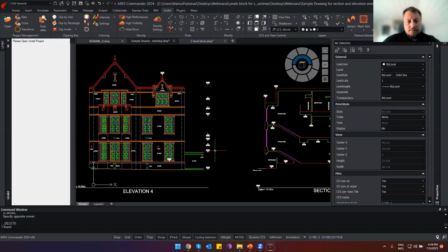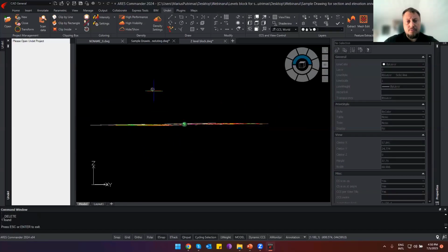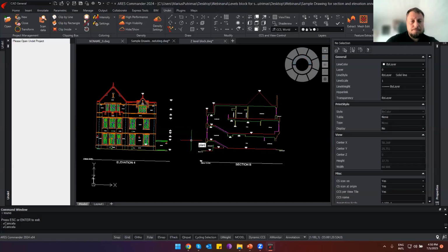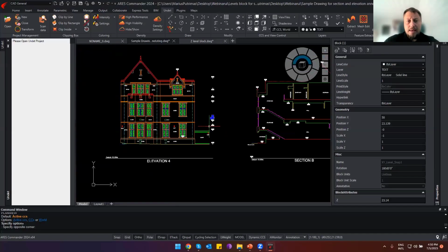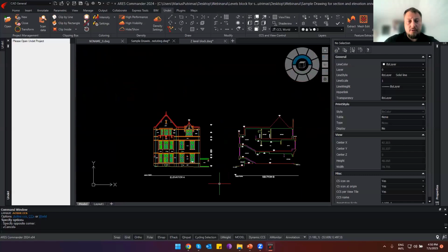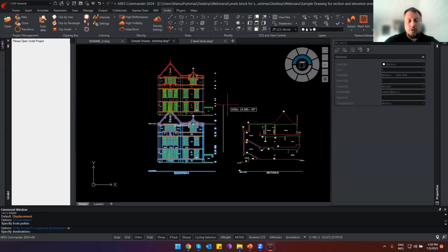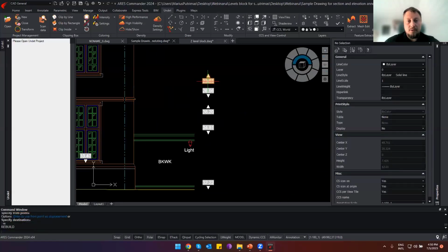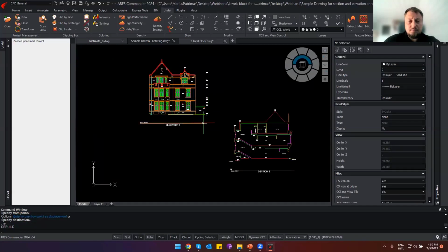And the last important thing, when you're delivering these drawings to the end user in DWG file format. You see now it's flat, everything is okay. But if you select these blocks, you will see that it's not a text symbol, it's a block. And if a customer accidentally moves your drawing relative to these blocks, these values will automatically change. So in this case, it's better to explode these blocks.